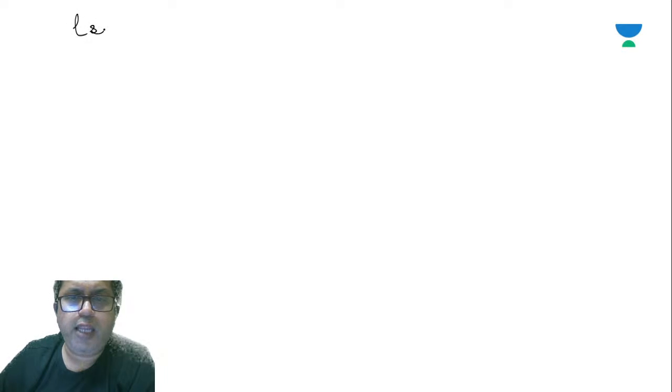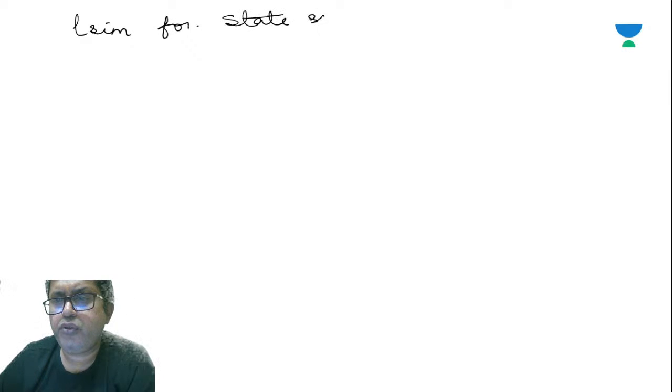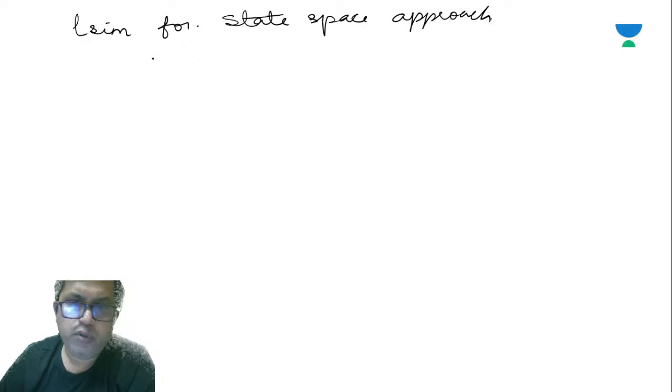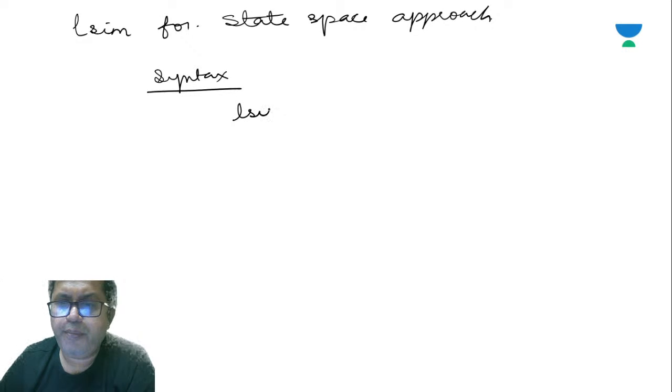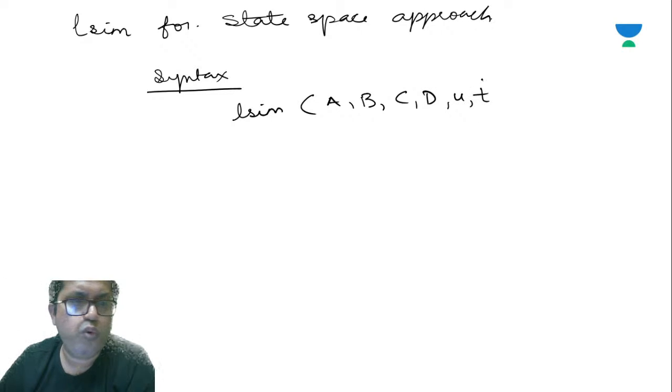Let us say LSIM for the state space approach. So what is the syntax? LSIM a comma b comma c comma d comma u comma t.